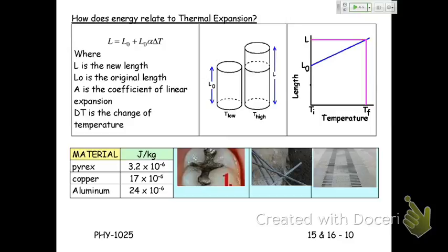If you think about it, in an automobile engine, you want some bits to be wear resistant, like your piston rings and the inside of your piston. You want other bits to be light, like you don't want a cylinder head that's really heavy. You tend to use different materials for different jobs within a single engine. And all those materials have to fit tightly together so that you get good compression at low temperature. And you can take your car to Alaska, it's going to get really cold there. Maybe you need a little heater for that. Or you can go to the desert and leave it all day in very high temperatures, and it's still got to work.